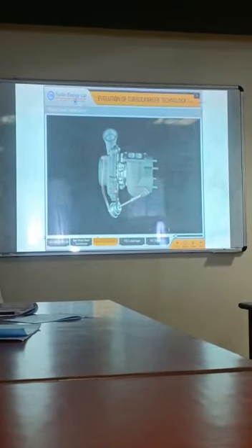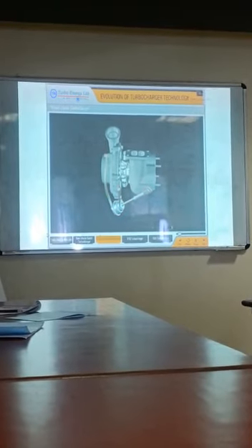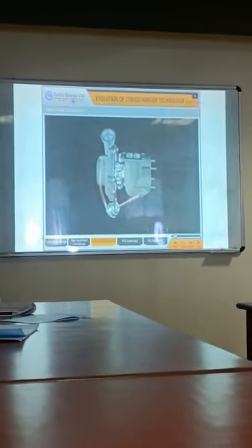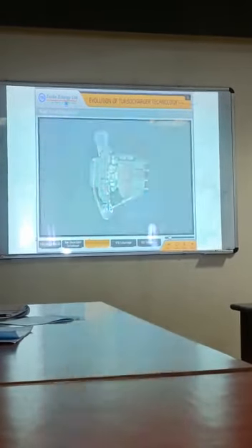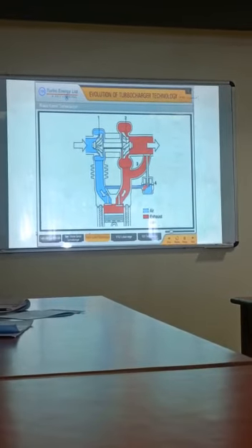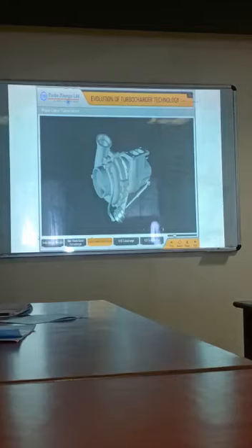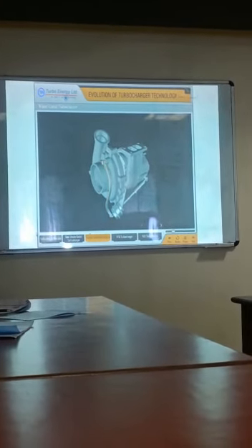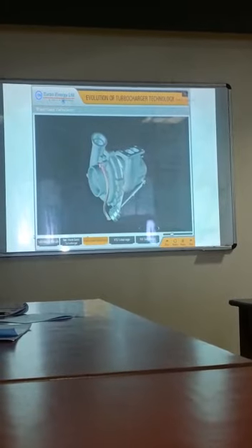Waste-gated turbocharger. A waste-gated turbocharger has an additional mechanism called a wastegate and actuator assembly. This mechanism will limit the maximum boost developed by the turbocharger. The actuator assembly has a spring-loaded diaphragm and is mounted onto the compressor housing. A hose connects the compressor housing with the actuator to ensure that the pressure in the compressor and the actuator is the same.